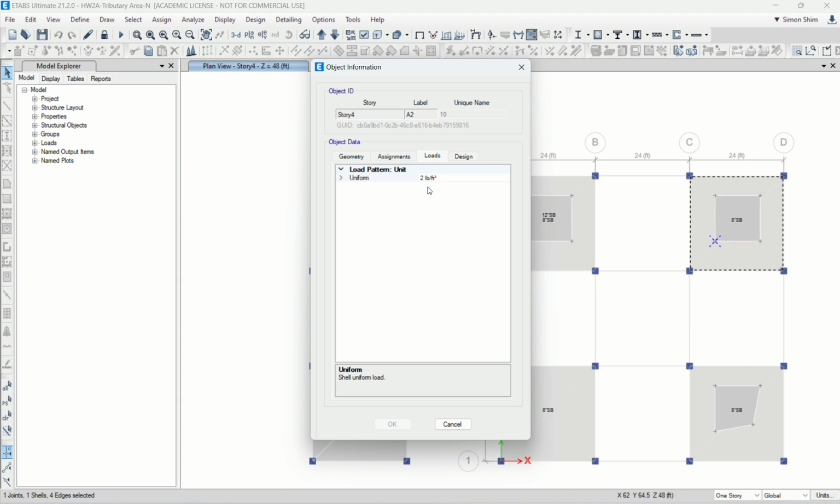If we don't have this feature, as I already explained, I need to find some equivalent area or use an average weight, average uniform loads, or we may have to mesh it. You know, physically mesh, right? And select this mesh and assign the 3 PSF here. Select all this outside area, assign 1 PSF. That is another method. You follow that?